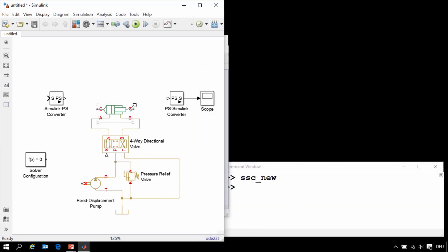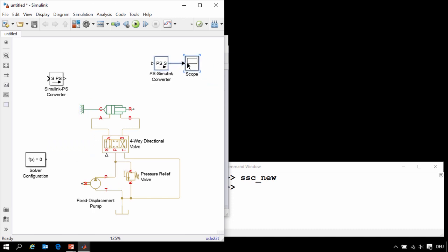These two mechanical connections represent the mechanical connections from our cylinder. We will connect this point to a point fixed in space. The other side is the rod which is connected to the piston in the cylinder. We wish to have this act against a mechanical load. We will click and drag to create a mechanical connection and then add a translational spring.